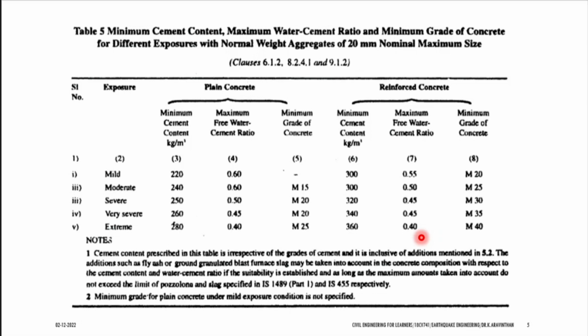They will not follow your words. You have to train them. When you say the water cement ratio should be 0.5, while you are there, they will use 0.5 water cement ratio. As soon as you leave, they will put more water and compact, and when you come back after it, the work will be over. And if you are using M20 grade concrete, what is the water cement ratio? 0.55.